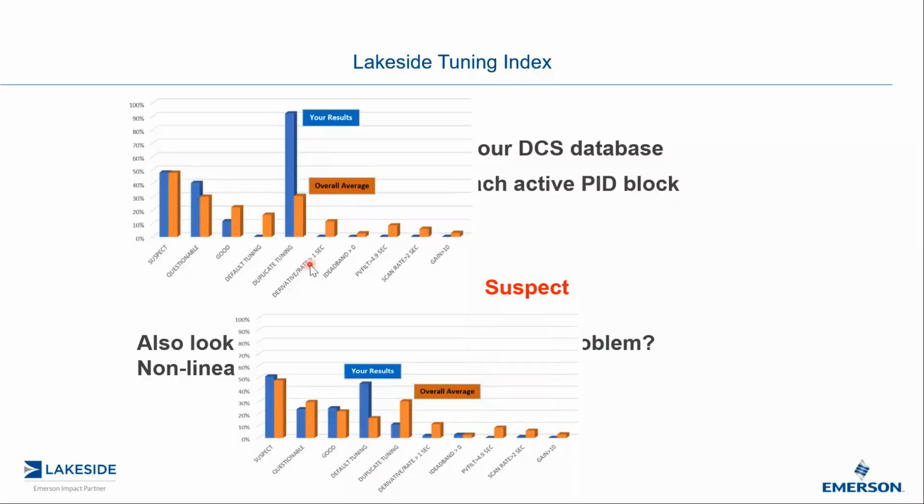Here's another one here. This is one of our customers. Almost 50% of the control loops, all the PID loops, had default tuning. That means they were never tuned. And actually, I've been there a few times now to go and actually address and tune those control loops.